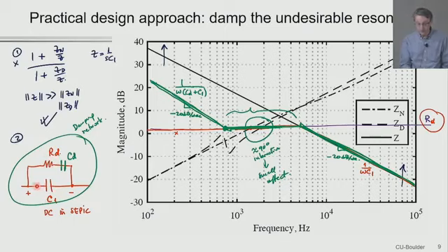Because the voltage across the capacitor C1 is not exactly DC. So ripple voltage across the capacitor C1 is going to be, presumably this one is large enough that ripple is going to be visible across RD. And so there is going to be some extra loss associated with this network. The loss is going to be small as long as the ripple component of the voltage across C1 is small.